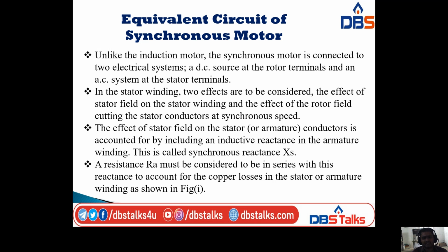The effect of the stator field on the stator or armature conductors is accounted for by including an inductive reactance in the armature winding. This is called the synchronous reactance, that is Xs.